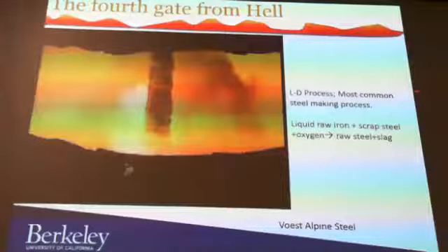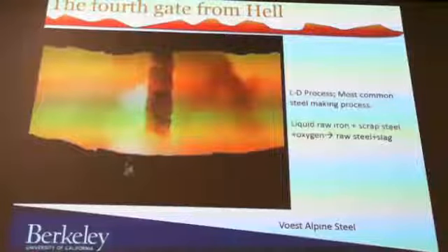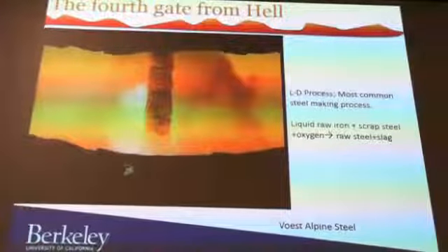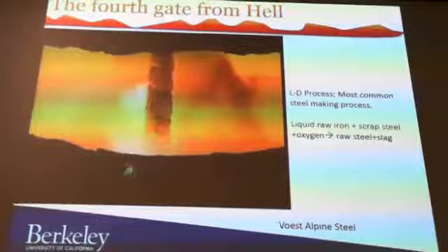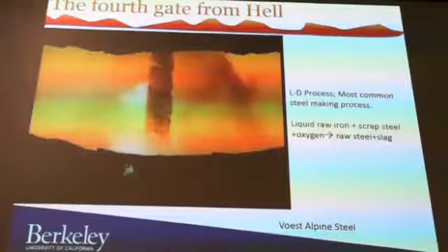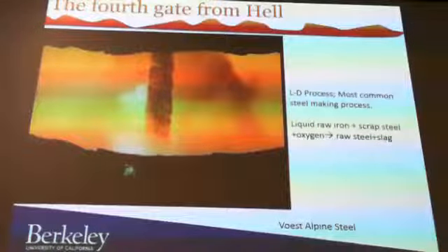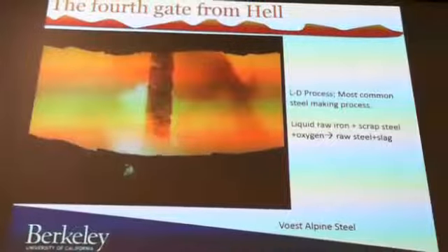You actually need scrap metal, scrap steel, in order to cool the process, because this is a highly exothermic process, and melting some pure refined iron cools the whole thing. So if you melt this, you take away the melt enthalpy from the process and cool the whole converter that way. So you really need scrap metal to do that, which has some other implications, because if you put scrap metal into steel production, you end up with some impurities scrap metal might have, like copper or sometimes radioactive sources people are not